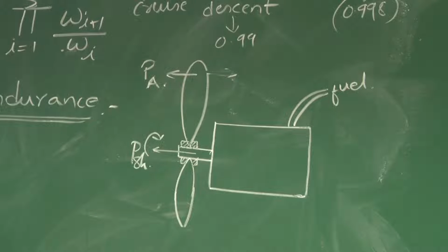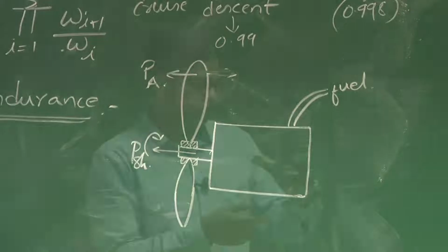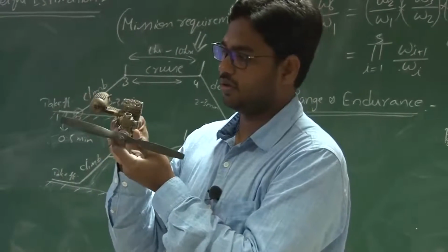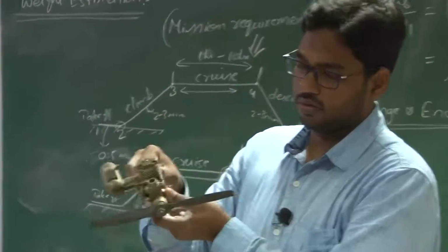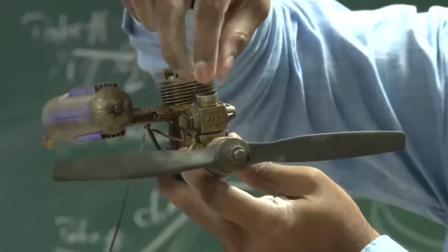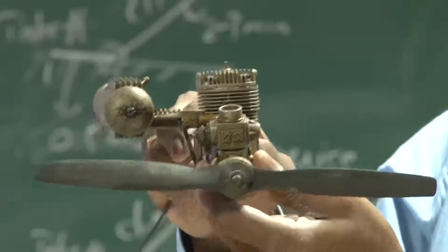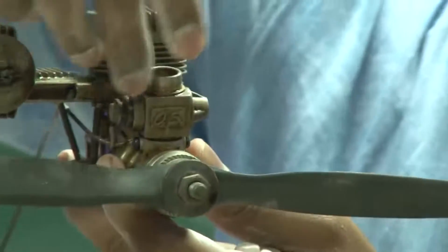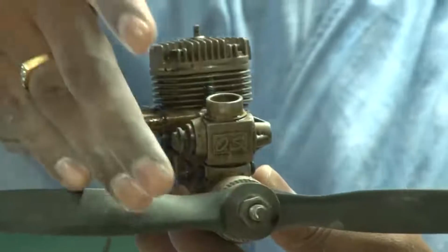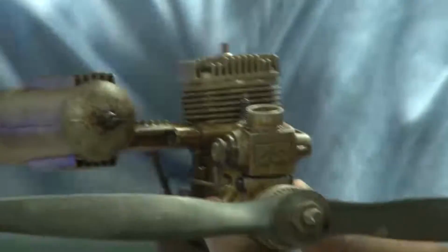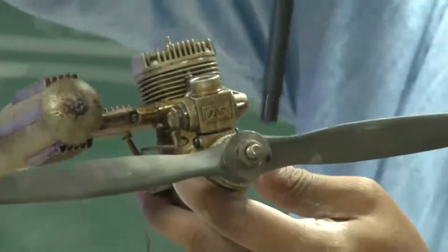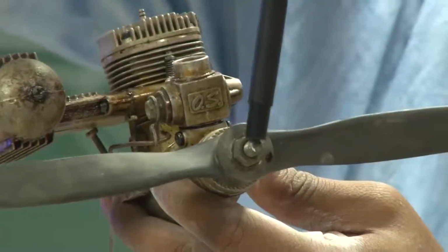Now let's have a look at it. It's worth showing this IC engine. It's a small IC engine, right? So this is a carburetor that controls the fuel air mixture, and there is a valve inside with which you can control this fuel air mixture and the corresponding RPM, and the shaft power. So what is shaft power here? The power that is available along this shaft, right?